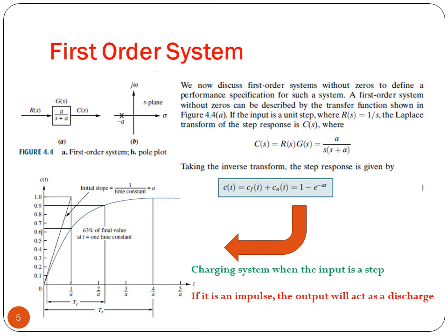For the first order, in fact, they consist mainly of a real pole. Also, it must be of a negative value in order to have a stable system. In fact, the stability will be treated in more detail in the next chapter. However, so far we only have to make sure that the system is stable in order to study the time domain response.